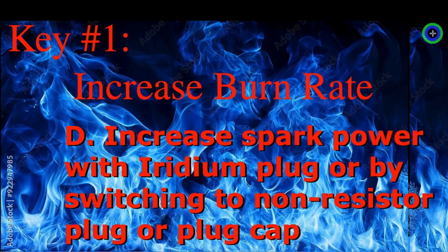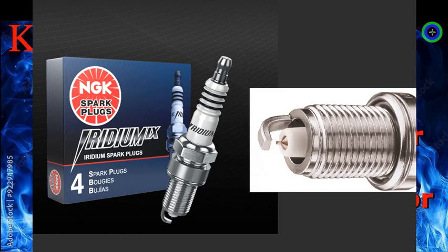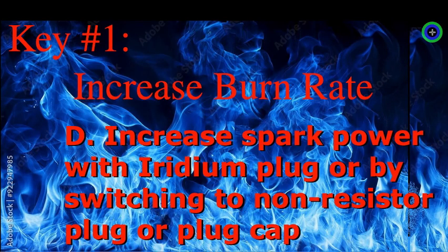D. Increase spark power with an iridium spark plug or by switching to a non-resistor spark plug or spark plug cap. It is a fact that iridium plugs require less voltage for the spark to happen.